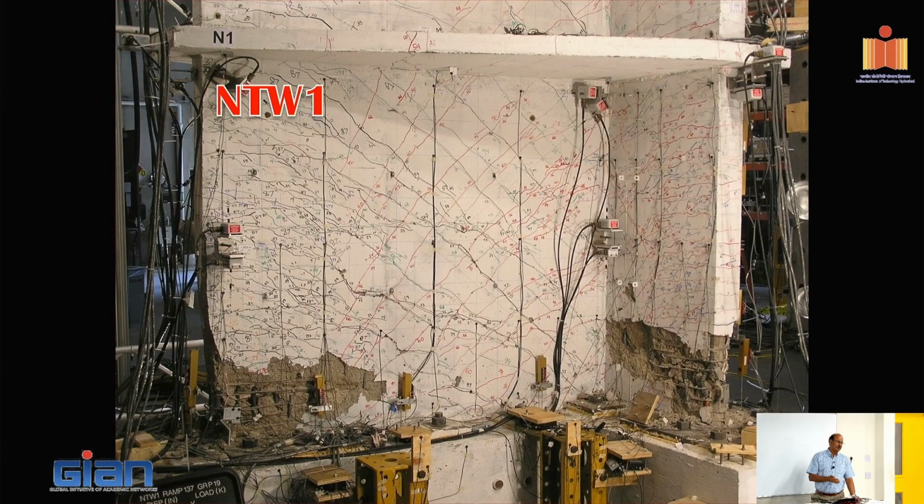One of the things that we have done in some UHPC testing is that the spalling doesn't happen because of the fibers. And when the spalling doesn't happen, the good thing is that the bars don't buckle. The bars stay together longer because there is no room to move around, right? So definitely they provide more ductility, but the compression strain capacity is a concern that causes some issues.